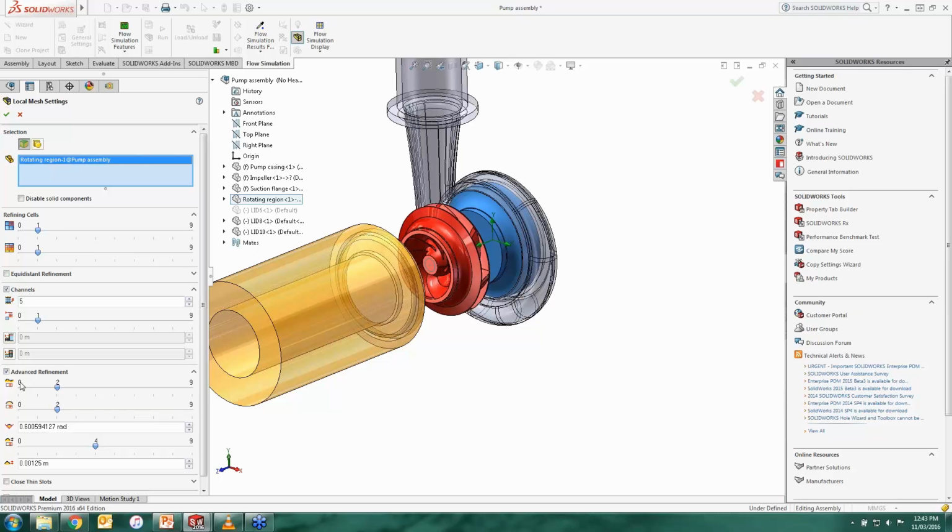Finer, better result, time consuming. 0 or 1, very, very coarse mesh, quick answer. Again, what is the best one? That is a simple procedure in all CFD analysis we have to take. We might have 2 comparative studies to find if there is any significant change based on increasing or decreasing number of elements. So as you can see, I have done my measurements on the geometry.